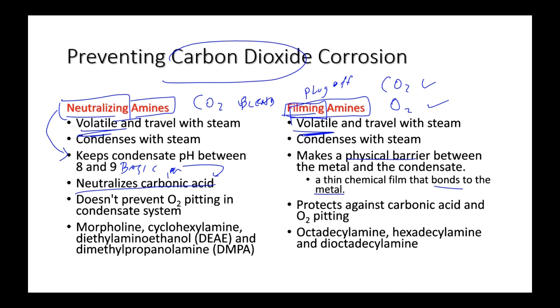But what I did was I looked at the trends, I looked at the charts, I saw that the master pressure wasn't changing, so I went to look at the master pressure transmitter, and I did a quick little isolation lockout. I removed that stainless line, and it was plugged with amine. I cleaned out all the amine. Meanwhile, I got the boilers on hand now, so that they wouldn't wander off on their own. So the boilers are on hand, and I isolated the plant master pressure control, cleaned out the sensing line, put it back into service. Meanwhile, I'm pooping my pants.